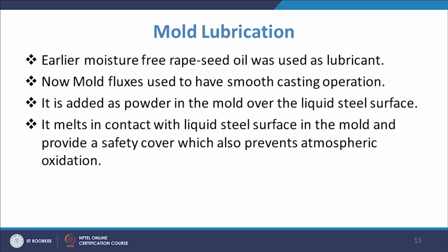You have a powder which will be given at the surface, and when it comes in contact with the liquid surface, it will be melted, and then it will go in between the mold wall, so there will be a layer of that lubricant, and that will ensure that there is no sticking of the surface. Another advantage is that it will prevent oxidation from atmospheric air. So, this is an example of these mold flux powders.